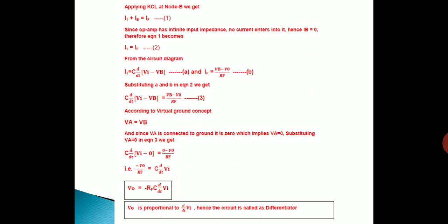So we have to write what current I1 is. We know that the current through any capacitor is given by C into dV by dt, where C is the value of the capacitor and V is the voltage across the capacitor. Here the voltage across this capacitor C is the input voltage Vi minus the node voltage Vb. The potential difference between the two ends of the capacitor, that is Vi minus Vb, is the voltage across the capacitor C. Hence we can write current I1 as C into d by dt of Vi minus Vb. We can call this equation A.